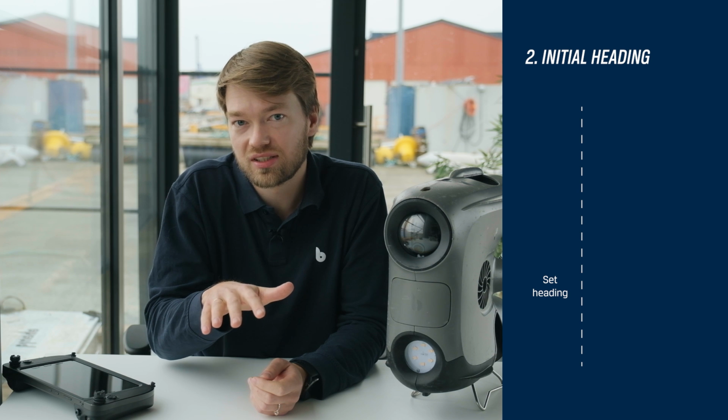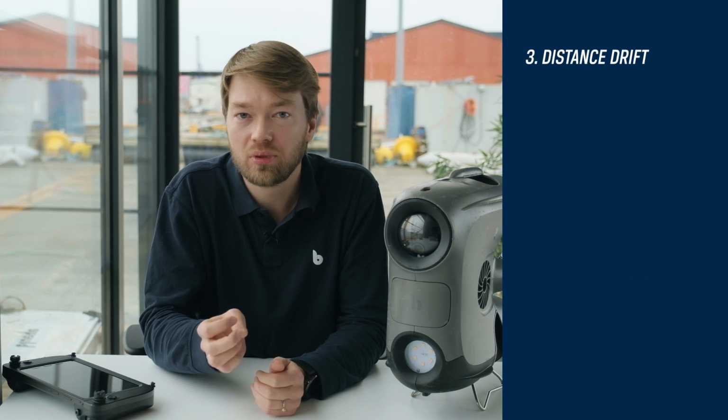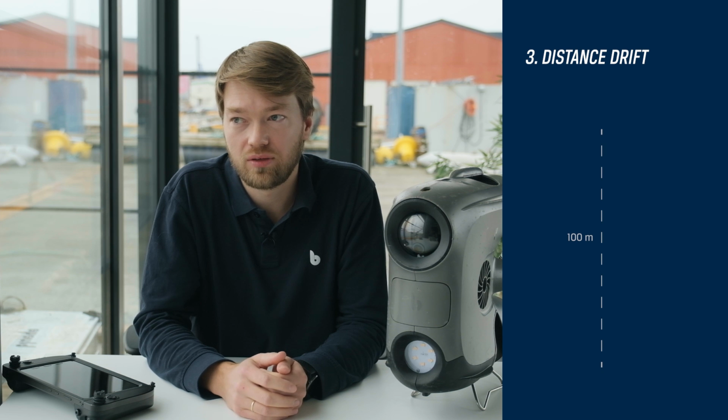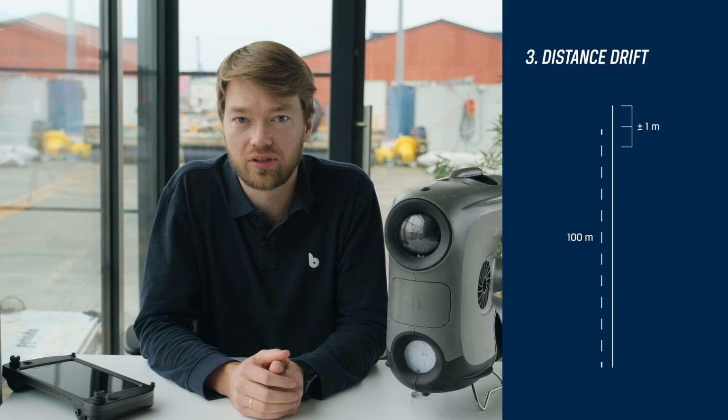The second component is the initial heading during reset. If this initial heading is off by 6 degrees, it will be off by 10 meters when you are 100 meters away. The third component is the drift in the accumulated travel distance. This is about 1%, which means if you travel 100 meters, you would be off by plus minus 1 meter.